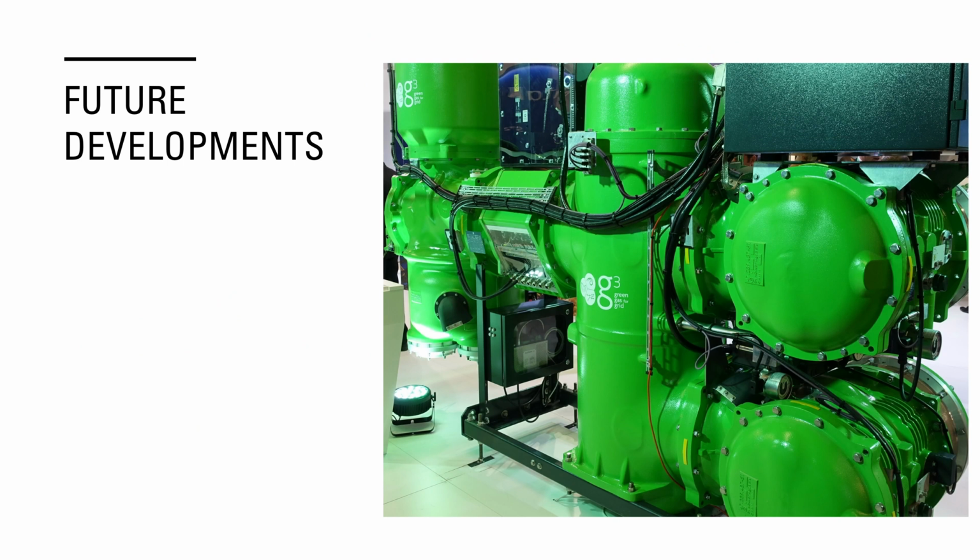If we look at some future developments, we're going to see the increasing use of high voltage DC for sure. The reason, as I said, is that we've developed all the easy wind farms now. All the ones that are close to shore, they've been done. All the ones that are in shallow water, they've been done. We're having to go further away. If we go further away, then the electrical losses in the export cable become a bigger factor.